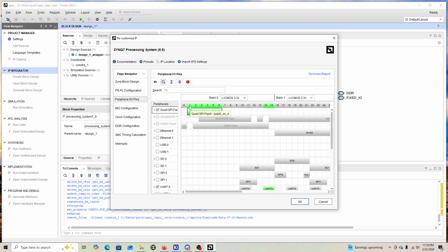With pin 1 being a slave select, 2, 3, 4, and 5 being I/O pins. That's basically our data lines, and MIO 6 being our clock line. So these pins are also bootstrapping pins, which basically means the processing system on startup samples these pins, and depending on their state, we boot from specific devices.